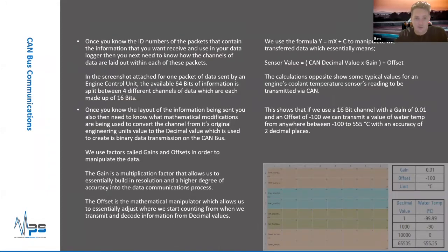Yeah, this just follows up the previous slides. But say CAN is a great tool if you're already in control of some of the other electronics modules on your car. I know plenty of people that have started to tune their race engine, gone to an aftermarket tuner, got an aftermarket ECU on there, and if you're in control of that side of it, CAN bus is a great tool and a relatively easy tool to use if you're trying to integrate a motorsport data logger. But it's just a bit of a beware.